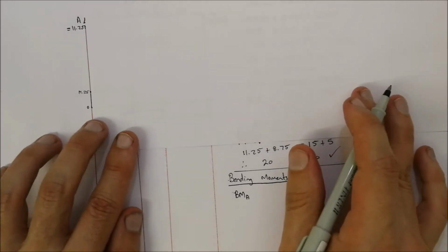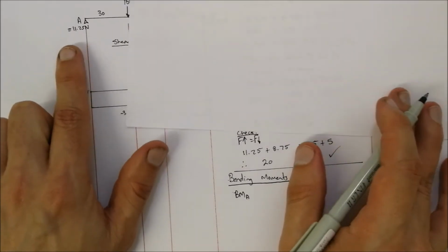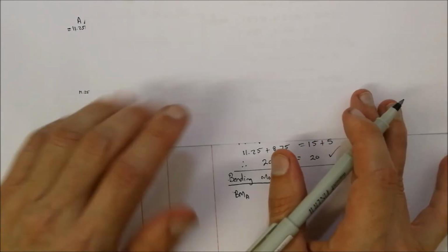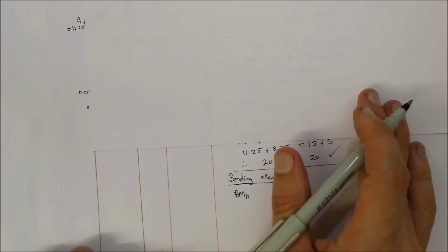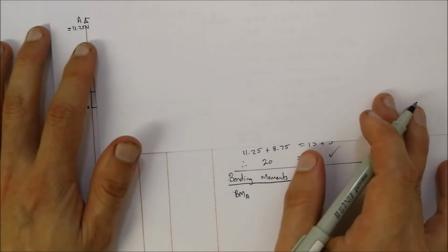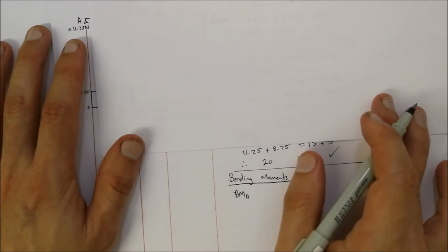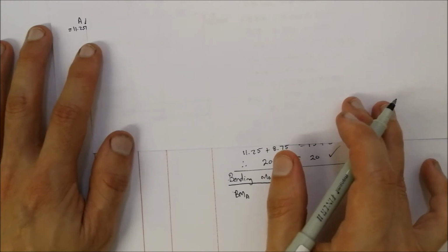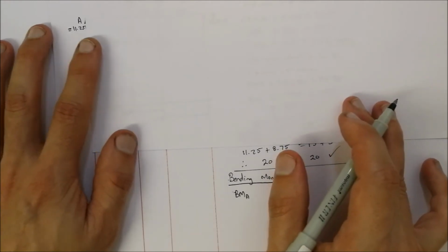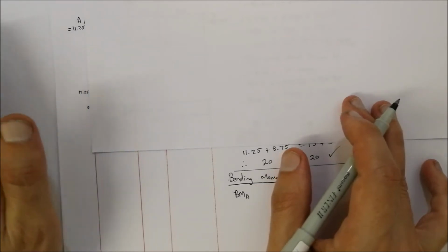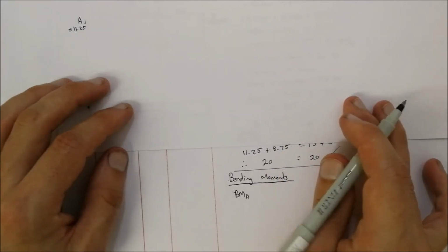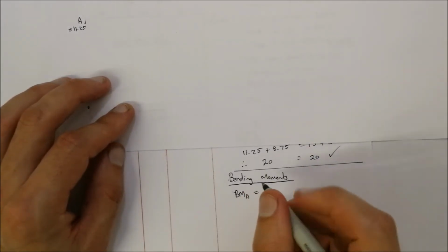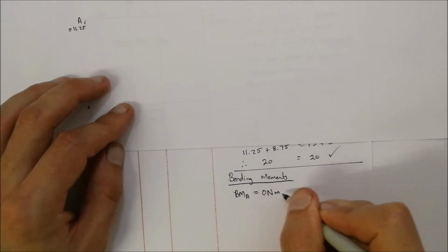Okay, so we place a piece of paper over our beam drawing over there, and we look at everything that's to the left of the sheet of paper. Okay, so in this case we told it that A is equal to 11.25, but the piece of paper is actually covering it at that specific point. We actually have to ignore it. Okay, so it's everything to the left of it, any forces to the left of it. Okay, so the bending moment at A is equal to 0 newton meters. Okay.